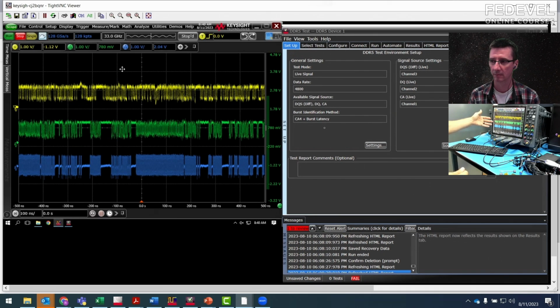But if you look at the screen, the data is the green signal in the middle. Can you tell which one is the read or the write data? I would say there will be a difference in how strong the signal is, maybe. Yep, that's true. Some of them are a little bit smaller, some a little bit bigger. Exactly. Some of them will be coming from the controller and the other from the memory chip. Wow, you have really good eyes. In fact, see this burst here? This burst is maybe a little bit lower in voltage than this one. Yeah, that's what I noticed.